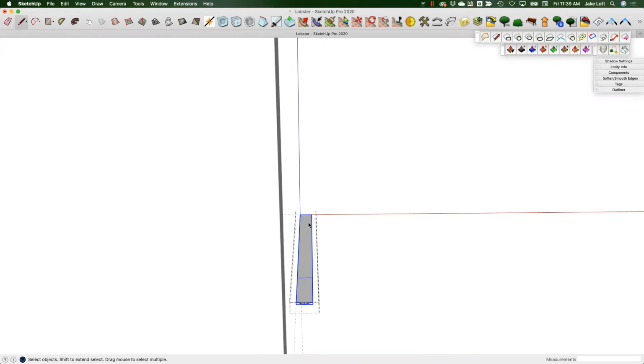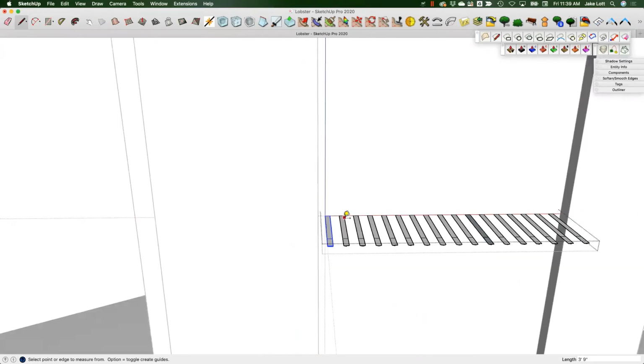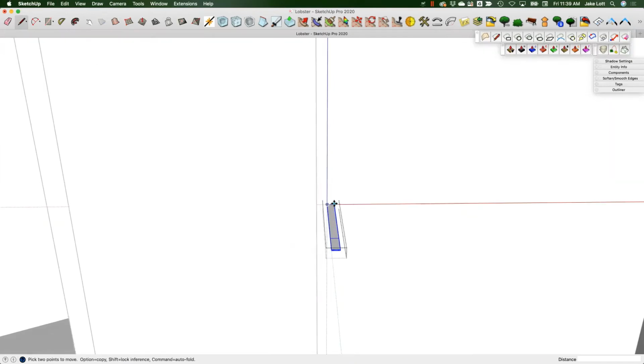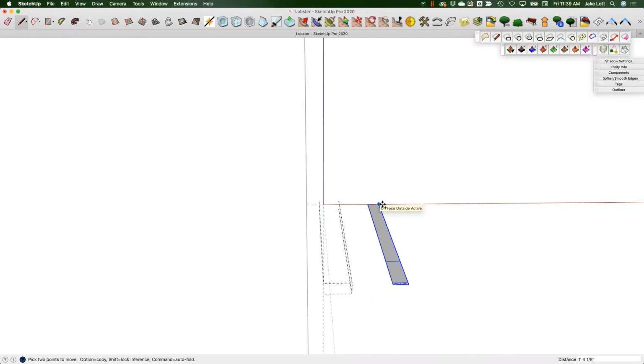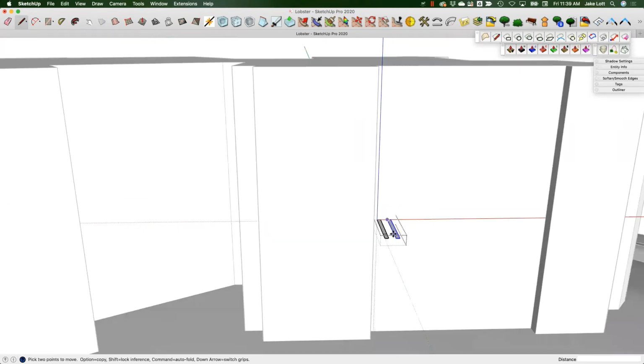I've got this component now, and I'm going to go ahead and move. Oh, I should measure properly. 11.5 inches. There we go. Okay. So if we take him and start moving him, press Alt in that direction there. Since we're nice and lined up in that group axes, we have that proper direction now that we can simply use that axis to guide us here. So 11.5 inches. And I'm going to go 12 times.